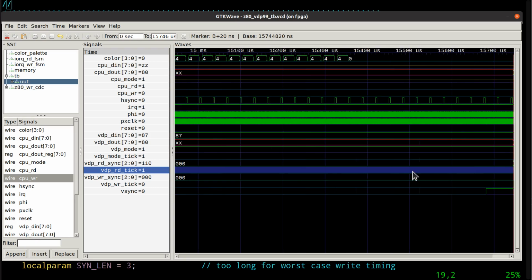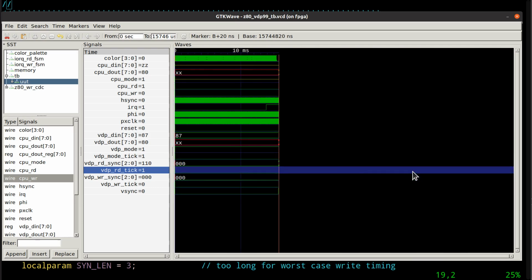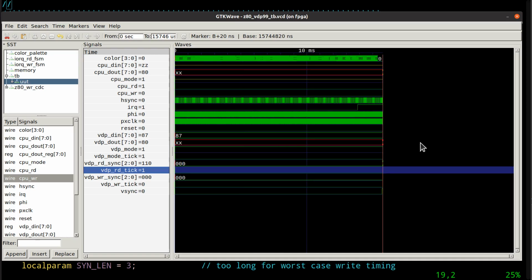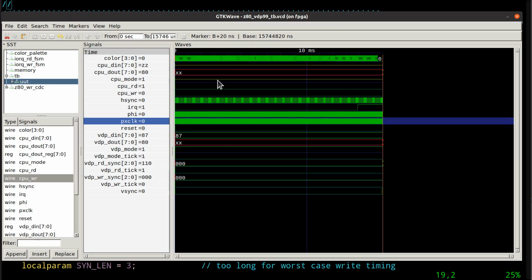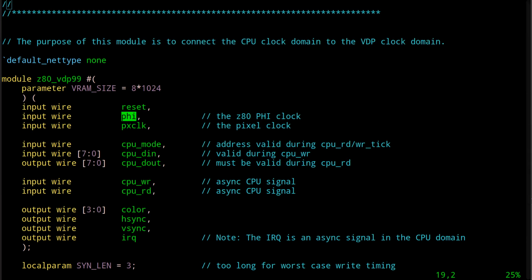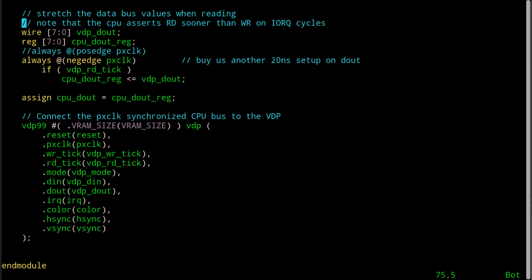If you play any games and the relationship of those clocks changes in the wrong way, where the CPU phi starts running equal to or faster than the pixel clock, the code that I'm giving you here will not work. So this is only good for old 8-bit CPUs, which is exactly what we've got, and it's nice and simple to understand, even though it probably took me an hour to explain it.